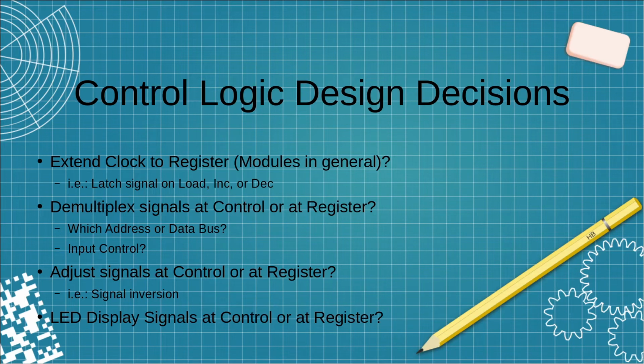The register then needs to assume that all of the blocks are in place, that when it has control, it can perform that assert. On the input, on the other hand, the register itself should maintain that control to assure exclusivity. That means that we would be passing on a multiplexed signal to the register, and the register would then need to be able to provide some protection to say, hey, I'm not going to do more than one thing at a time, because it could end up hurting the hardware or giving indeterministic results.